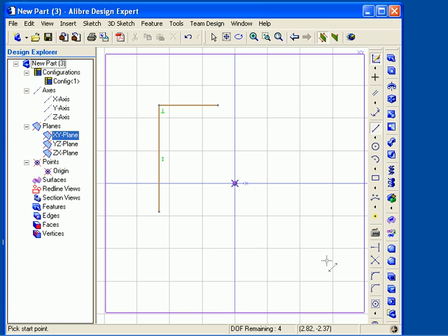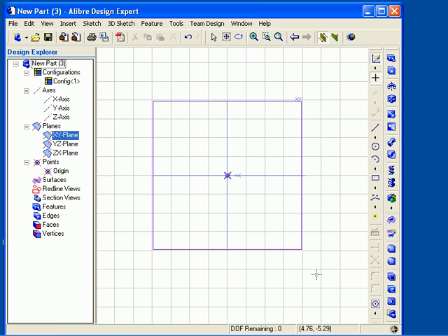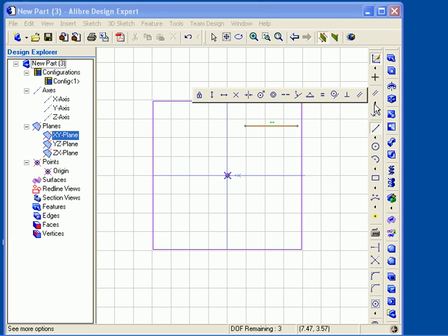I'm now going to introduce you to all of the constraints and show you how to apply them manually. You will want to become familiar with all of these constraints. The constraints are all accessible from the sketching toolbar. The constraint tools are not active until there is at least one sketch figure placed in the work area. You will see the constraint flyout if you click on the Options arrow.